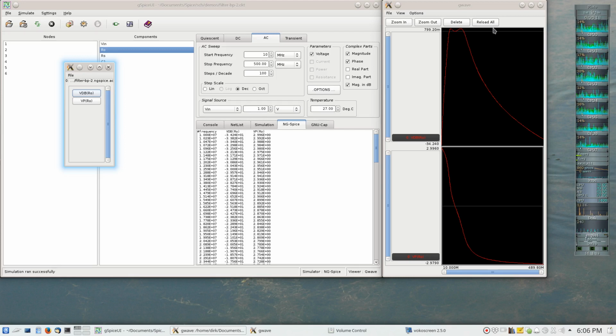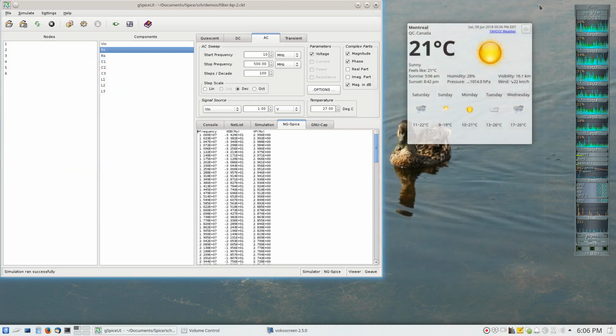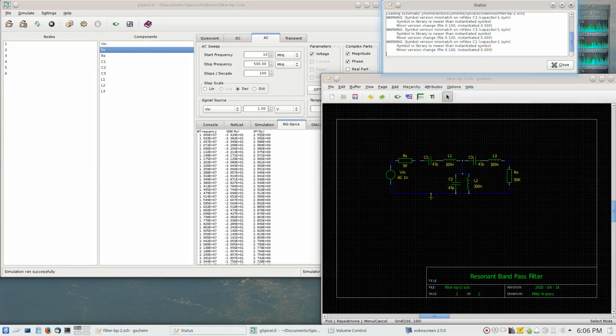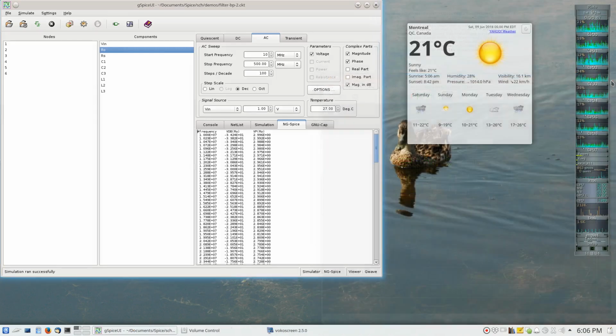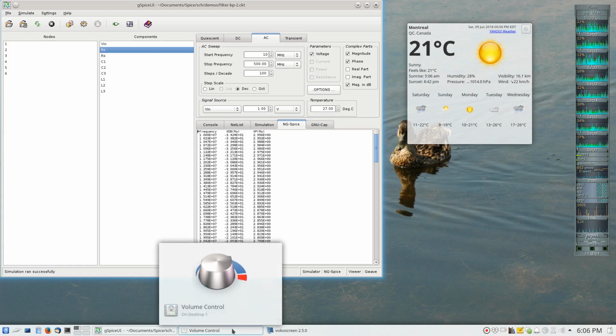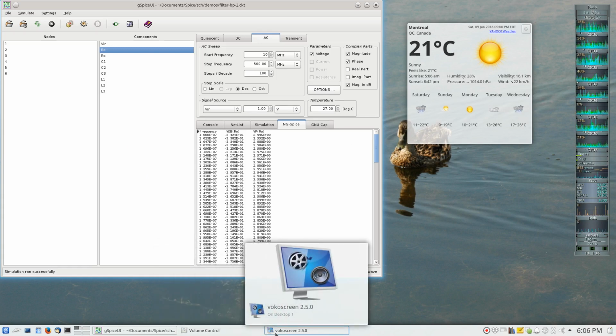So the thing is that while we have this software to play with, we don't necessarily need to build a circuit. We can construct a schematic of a circuit, and the schematic of our circuit can be edited using another graphical user interface called GSchem, which stands for Schematic Editor, again by the same group of programmers. And here is the circuit that we just simulated. So we have options as to how to use this, but sometimes the instruction manuals don't tell us quite enough on little details like having to drag a button into our oscilloscope view.